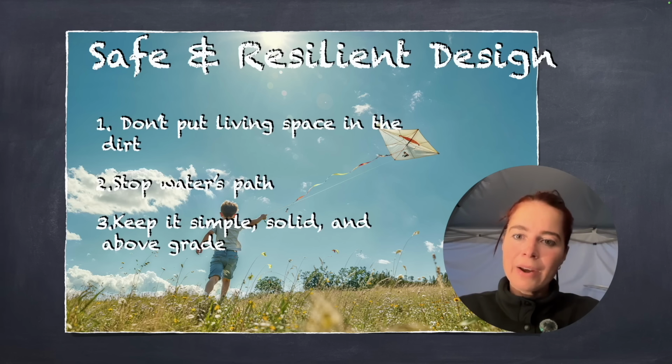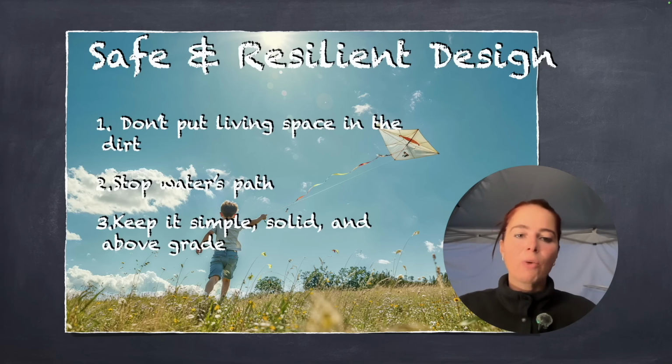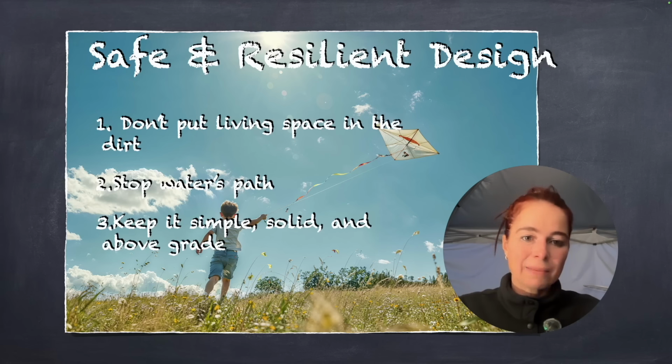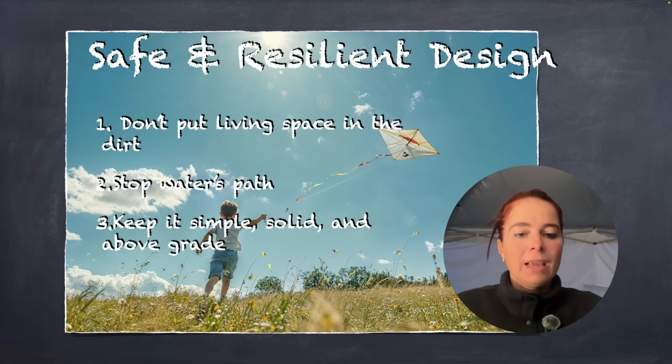So I want to end on the note of what lessons we can take from this. My aim is really to help you find a way to create a home that's safe and resilient, based on safe and resilient design. So first of all, don't put living spaces in the dirt. Secondly, stop water in its path. So use capillary breaks between the soil and walls. And a rubble trench is a capillary break in and of itself. And keep it simple, solid, and above grade.